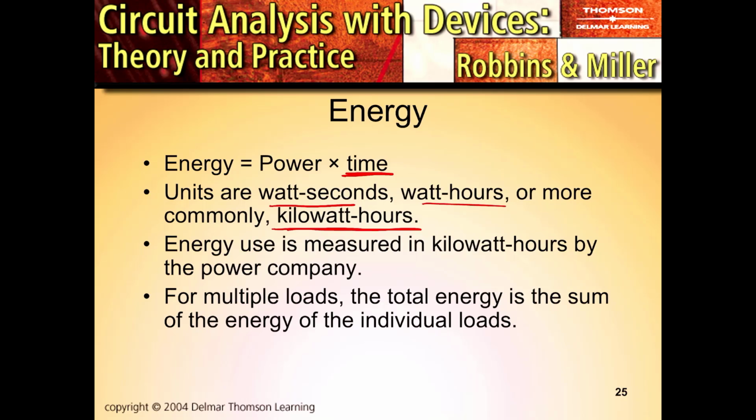So energy use is primarily measured in kilowatt hours by your utility company, and that's why when we do these cost of energy equations and any calculation of total energy, we use kilowatt hours. So we're going to convert our power values to kilowatts right away to make it simpler. So for multiple loads, the total energy is the sum of the energy of the individual loads.